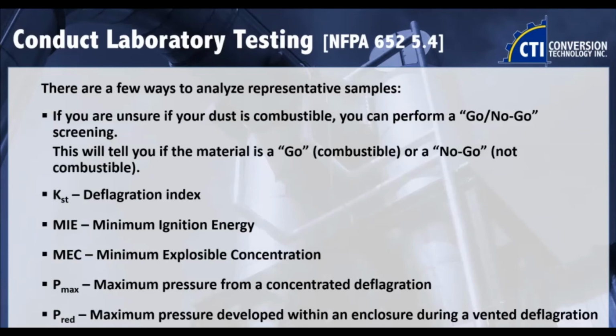One question I got recently was, without getting all this tested and knowing how much dust is in the air, how do I know? It's pretty interesting. It's basically if you can't see a light bulb 6 feet away, that's the dust cloud in the air. Dust on a surface, which would be a minimum ignition temperature, like dust-coated motors, that's a little bit different. The standards do specify a very shallow depth allowed of dust on surfaces, but this is more in the air.